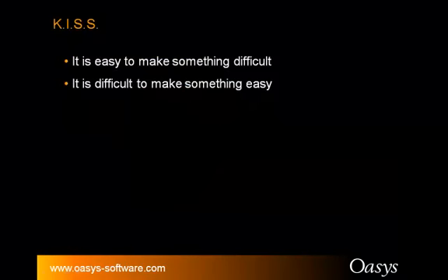First one, very often forgotten. Try and keep it simple. Classic mistake is people start off trying incredibly complicated models, and it all goes horribly wrong because they've got too much detail. Basically, if you're modelling an overall structure, keep it simple. If you want to model something to get detailed results, then do a small detailed model. It's obvious when you think about it, but it's often forgotten.